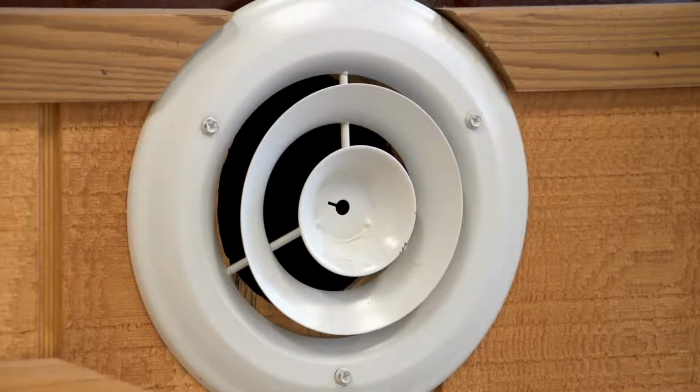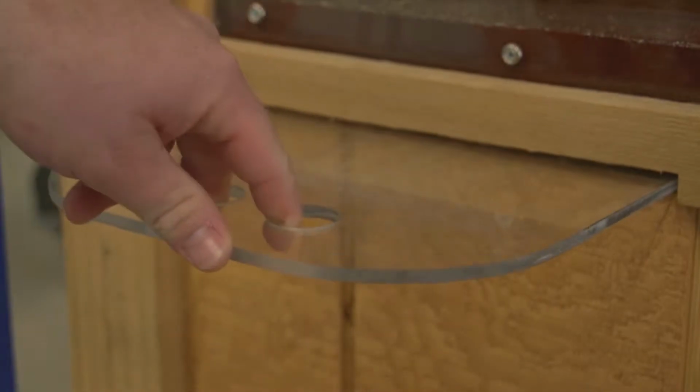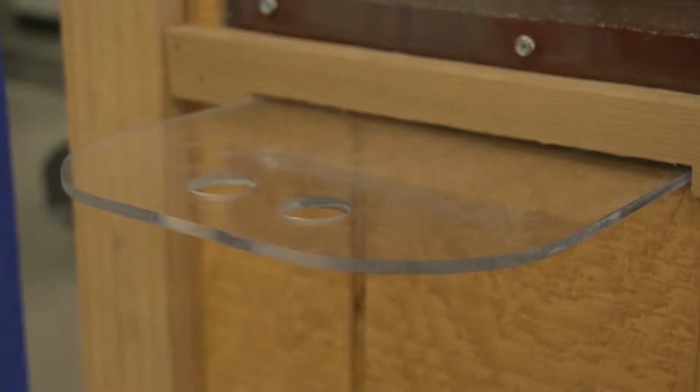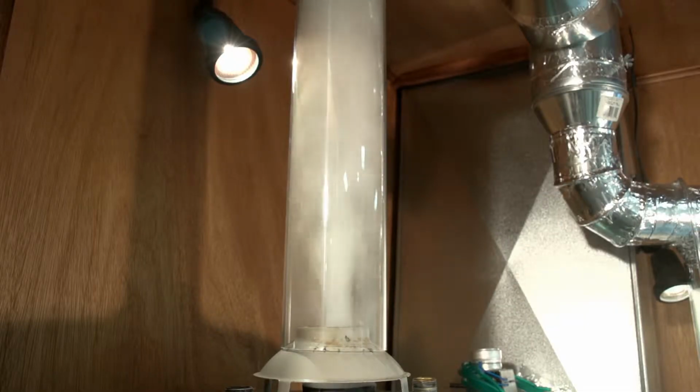We're going to add a little bit more makeup air to this home now. We're going to do that by means of a passive vent, which I'm going to open in the front. It would appear that the combustion makeup air that we've added has been sufficient to fix our CAS problem.